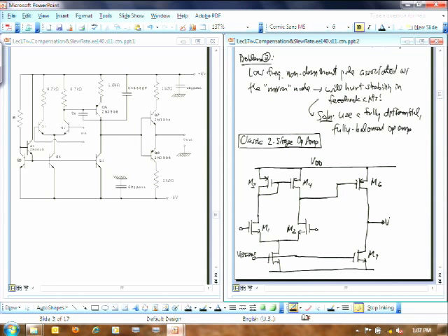What that capacitor is doing is making sure that this op amp stays stable in certain feedback circuits that it's used in. Okay, that's something we're going to talk about at great length in the weeks after spring break. I'm going to say a little bit about it here, just a functional thing that allows you to finish your lab. But it's really after spring break that we'll talk in great detail about compensation.